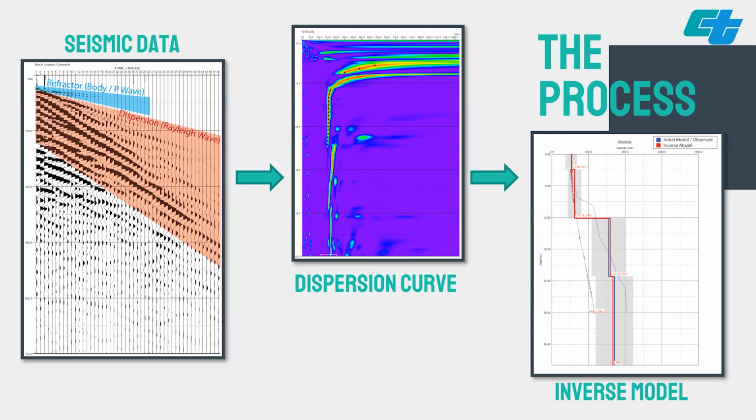Here's a look at the process of surface wave data reduction and interpretation. The seismic shot record on the left contains information about Rayleigh wave dispersion and body wave refraction. This seismic data undergoes a wave field transform followed by Fourier transformation in order to derive the phase velocity as a function of frequency. This phase velocity as a function of frequency, seen in the middle image, is the data from which a dispersion curve is picked. The picked dispersion curve is then used in the inversion modeling algorithm to develop a model of the subsurface velocity sounding from which VS30 is calculated, as seen on the right. It can be seen clearly here that pivotal to the creation of a valid velocity model is the effective acquisition of seismic shot records.